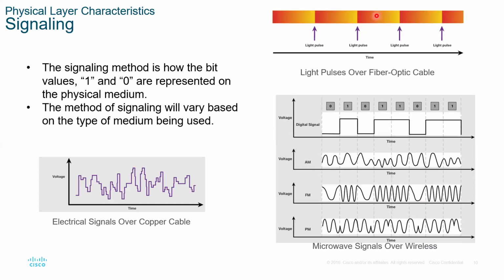Our messages have very low frequencies. And what happens when low frequencies travel long distances? They get attenuated. That is the reason you wouldn't be able to hear me on the other side without a microphone, without my message being modulated with a high frequency. It's because it gets attenuated. Now we need a high frequency signal to transmit the information. So in this case, it is a high frequency signal for radio, and for light, and here we have a voltage at a high frequency.